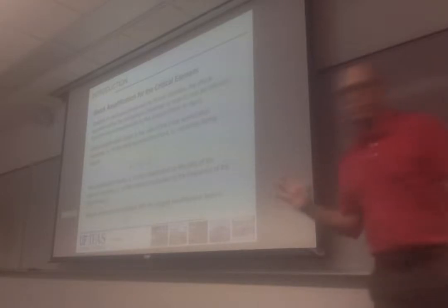We also discussed a little bit about shock amplification. So let me just review that one more time so we understand what's going on. This is very similar to the magnification factor. That's why I did not go into great details on it. It relates the acceleration that is felt by a critical component to the acceleration that is associated with an impact.